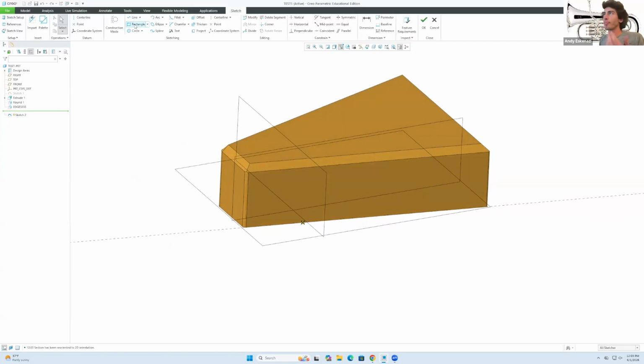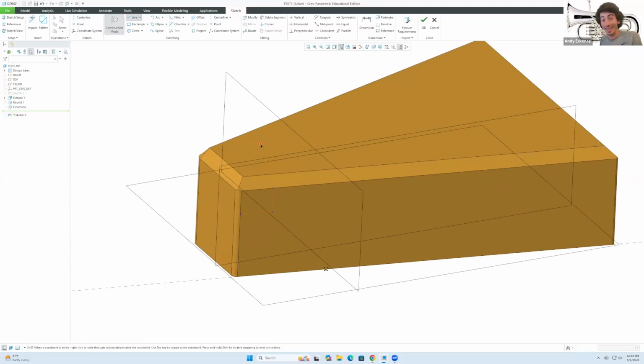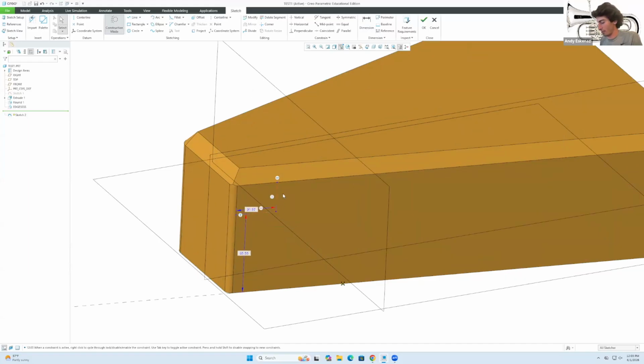So what about drawing a rectangle? Suppose these are my requirements. I want a rectangle whose edge is 5 centimeters from here and 5 from there. How would I draw that? Well, you would go here to line, but I'm gonna go to this that's called construction mode. So I'm gonna draw a little line that goes like that, and another one that goes like that. I click on escape, then letter D. Well, actually, it's already defined for us, but there we go.